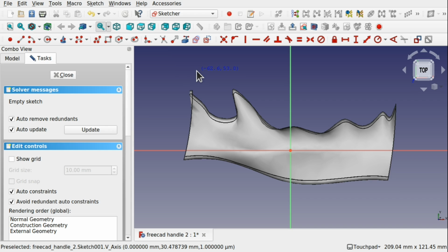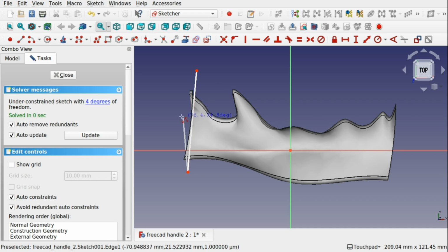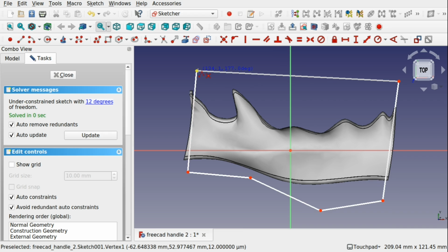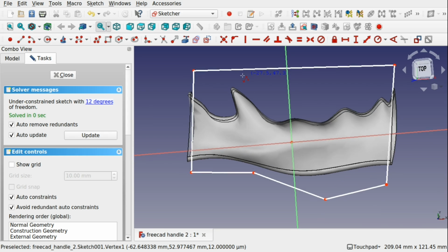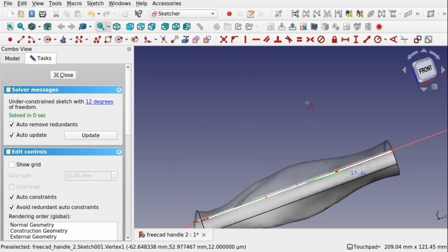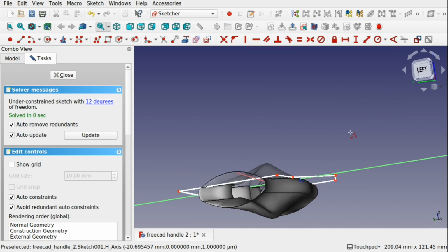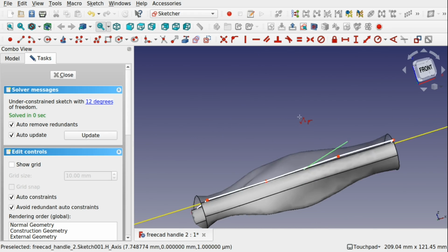And I'm going to cut right through this to make it planar, making sure the bottom of this pokes out the other side. And we can make any shape we want along here, like so. And I'm going to do the same for this bottom, making sure we cut through and connect up to the top there as well. So we've got those, and they slice through that knife. Still got the transparency on, so that's fine.